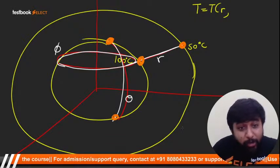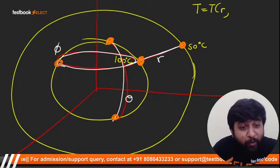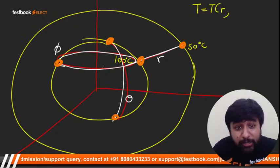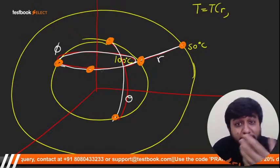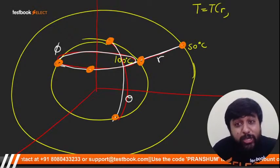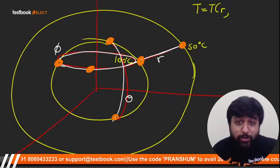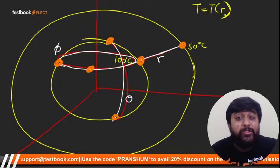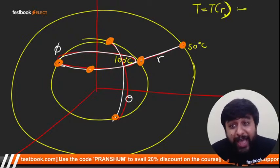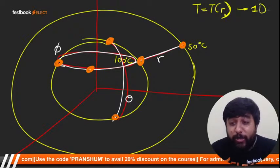And similarly, you take 2 points along phi. What is this temperature? 100 degrees Celsius. What is this temperature? 100 degrees Celsius. Inner surface. So temperature is not a function of phi also. So temperature is now a function of only one space coordinate. So this has become 1D function now.